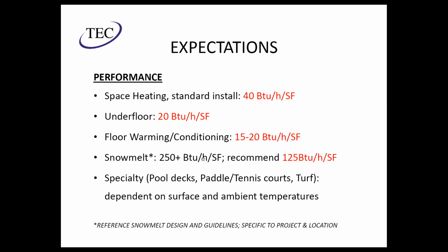And then snow melt can go as high as you want it to, really, but we typically recommend around 125 BTUs per square foot for this region. There's all sorts of specialty applications that can be applied to this. In those situations, you really want to get involved with the manufacturer so that they can help you identify any particular problems with those installations or anything you need to look out for.